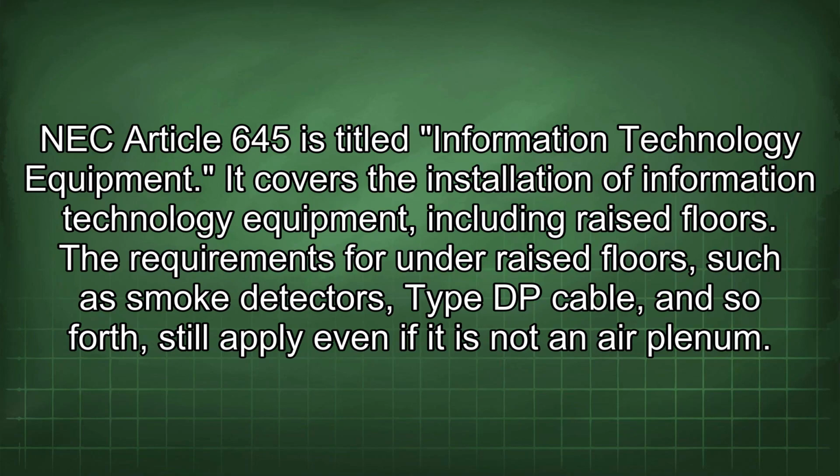NEC Article 645 is titled Information Technology Equipment. It covers the installation of information technology equipment, including raised floors. The requirements for under raised floors, such as smoke detectors, type DP cable, and so forth, still apply even if it is not an air plenum.